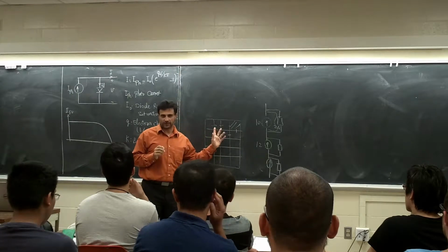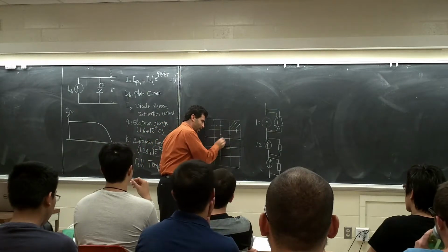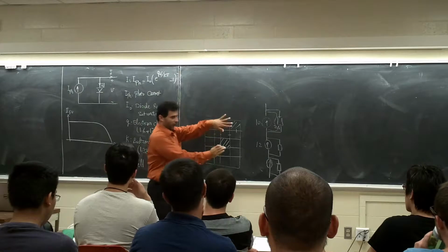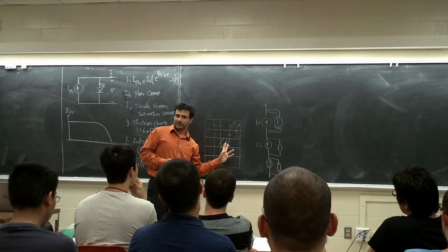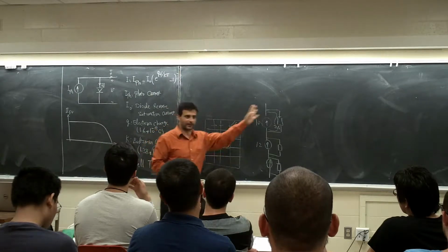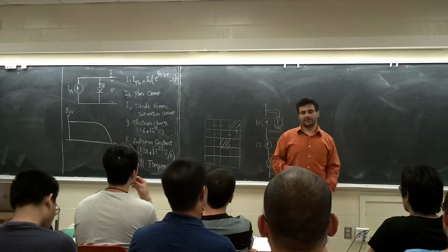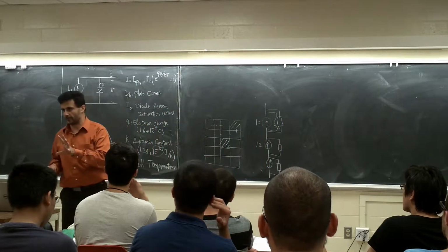Hopefully if we go for this visit, I can show you, we have it here. They put one small inverter behind the panel, this is the front. So this inverter is going to control this panel, connected to the next panel. Basically they do the maximum power point tracking per panel.